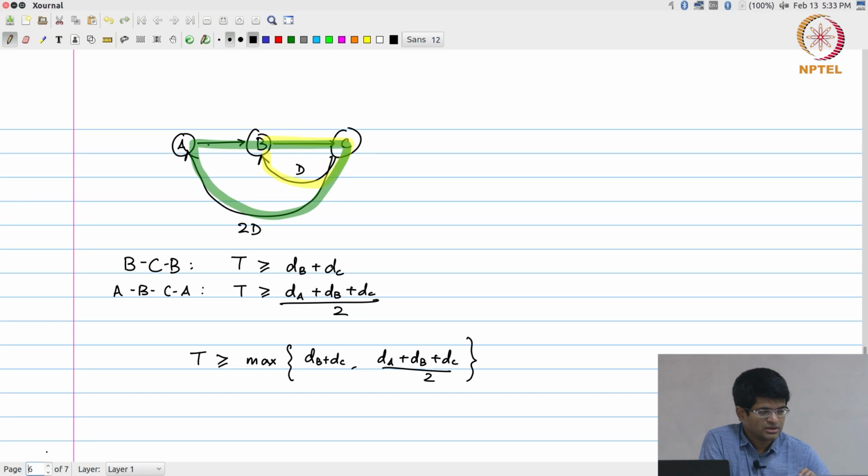Okay. So, like I said, this is sort of the theoretical basis for what is the best possible performance that I can get out of a given data flow graph under a certain constraint of technology. Keep that in mind, my D and A values are constrained by technology. So, in other words, if I move to a better technology, right, 28 nanometers, 20 nanometers and so on, I will probably end up with faster execution units. That itself is sufficient to reduce my value of t, but that is not what we are interested in. Okay. Subject to this constraint of technology, this t is a property of the data flow graph. It is a theoretical minimum bound.